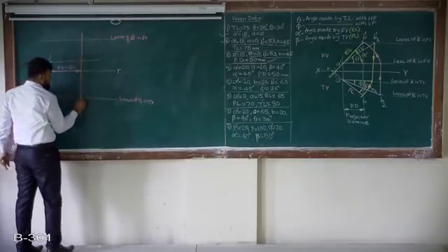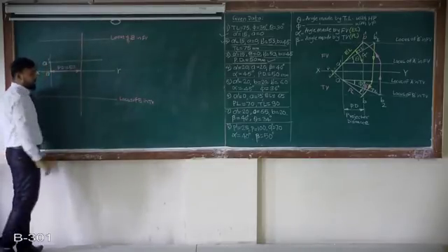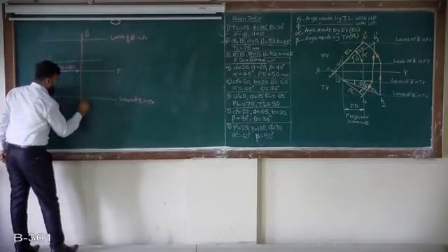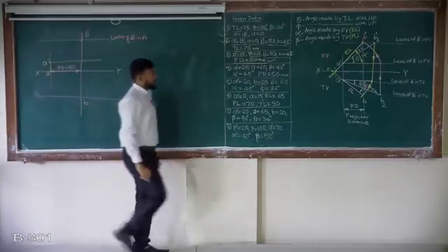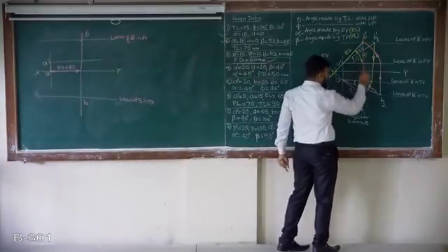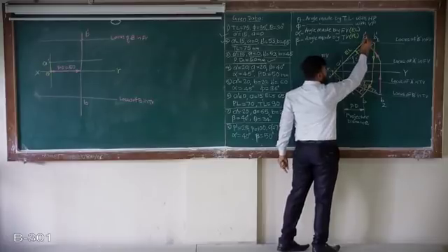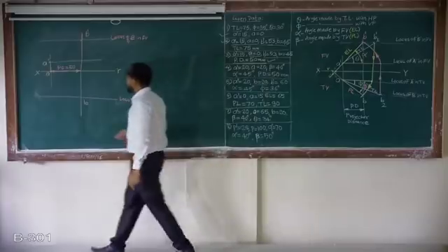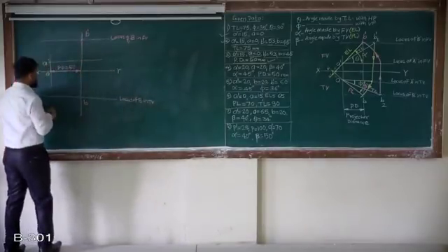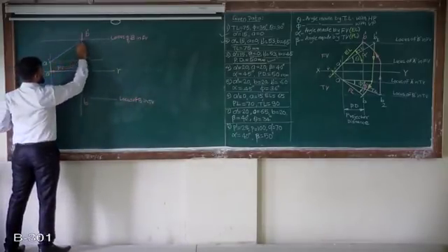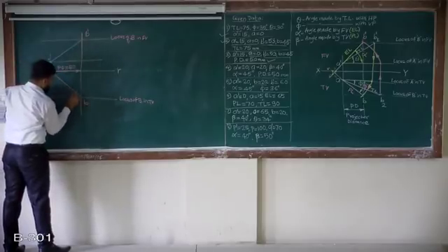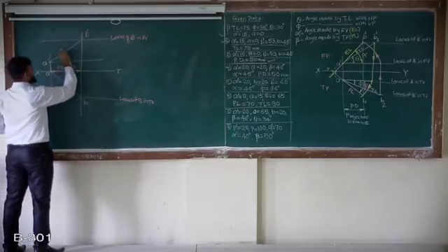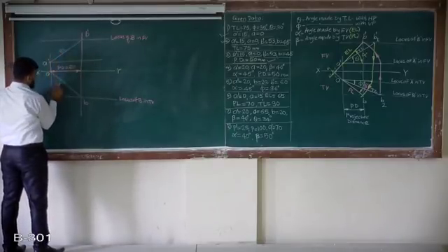Wherever this projector distance line cuts the locus of B in front and top view, I will get the points B dash and B. Can you see that this projector line cuts the locus at B dash and B? This is A dash A, and this is B dash B. Just join it. Now this is the apparent length, that is elevation length, and this is the plan length.